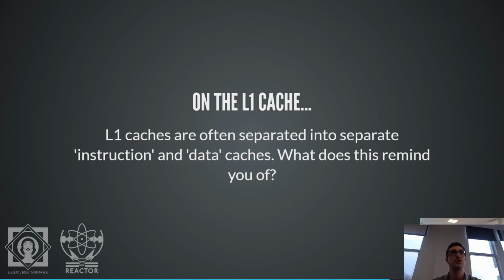And that's something you'll come across a lot in CPU design. We've been talking about things like RISC versus CISC. In practice and pragmatically, you have to make trade-offs. So even many RISC CPUs today will have complex instructions for very specific use cases of data processing. A good example of this might be operating on vectors of data, having specific instructions for doing an operation on 4 floats at the same time instead of doing 1. So trade-offs are always where you're at when it comes to any kind of design.